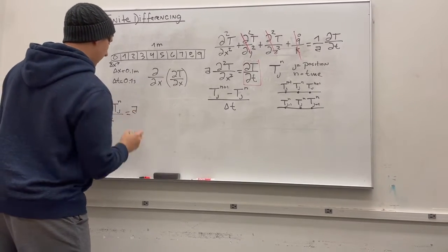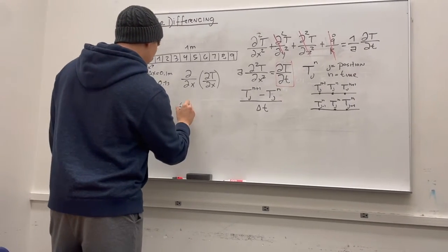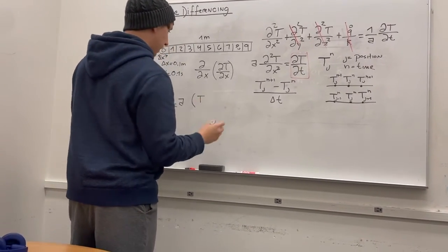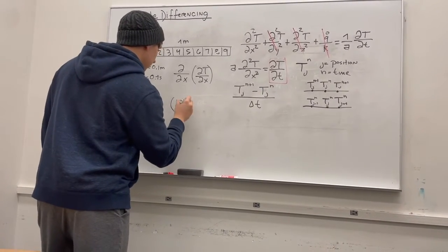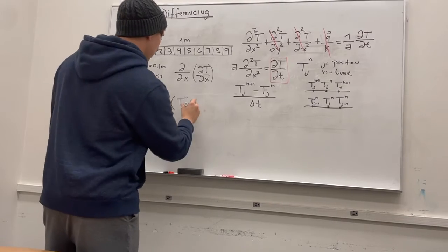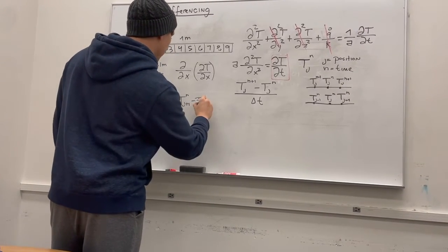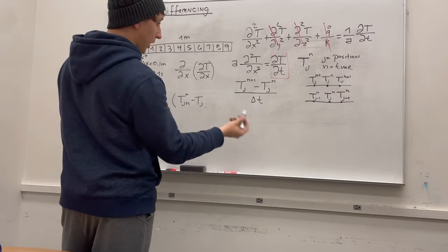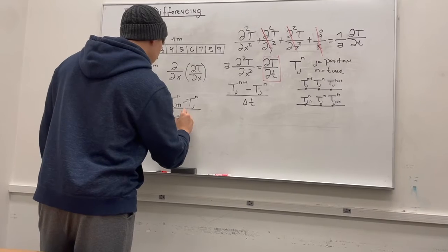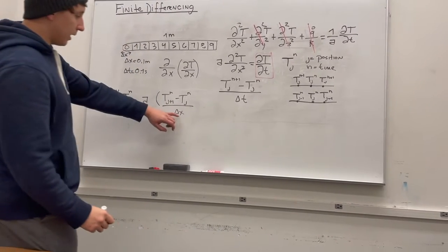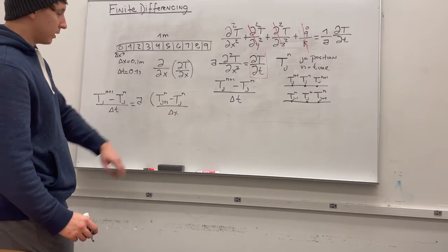We will have the temperature at some position ahead, keeping that time, minus the temperature at the position that we are establishing and trying to look at, keeping that time the same, divided by the change in the increment that we decided on, which was 0.1.